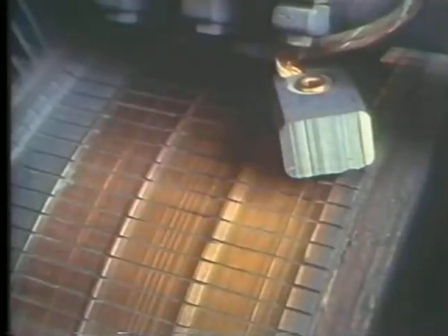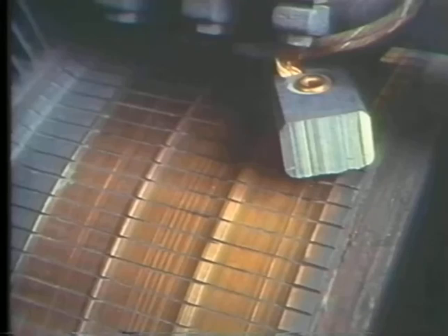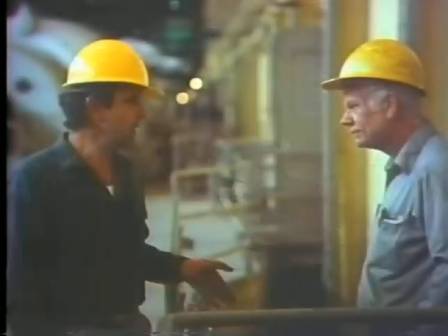And if the commutator that the brushes are riding against shows signs of wear, like this, then you wouldn't want to stagger these brushes. You can see why. The brushes and the commutator have formed wear patterns. If you move the brushes, they won't make full contact with the commutator. Instead, you should inform the foreman that both the brushes and the commutator are going to need attention.